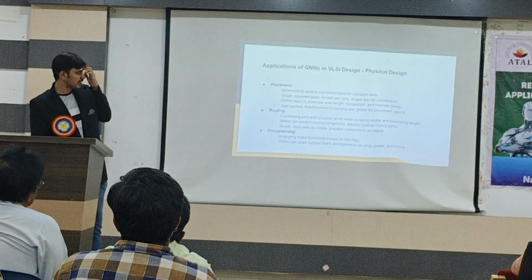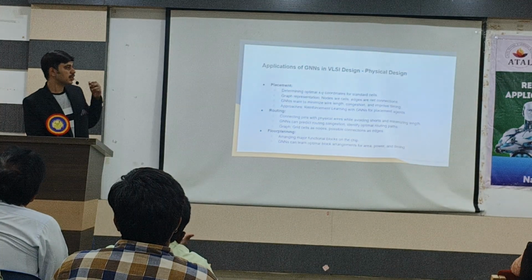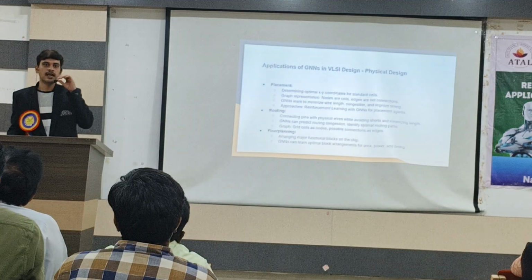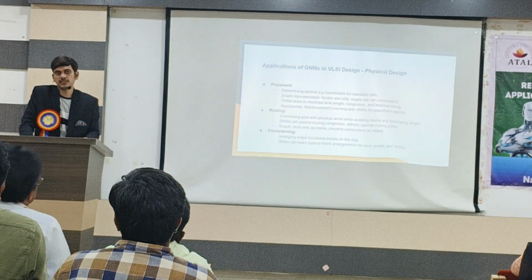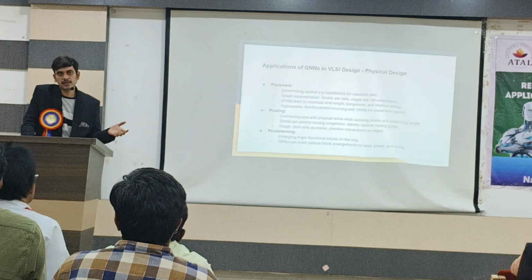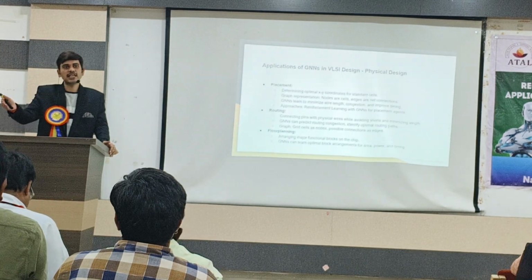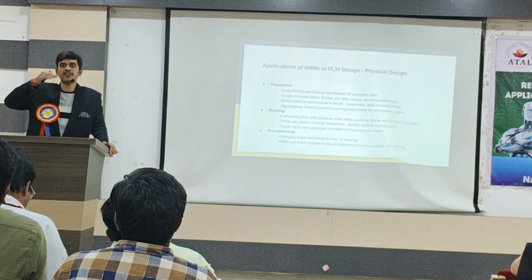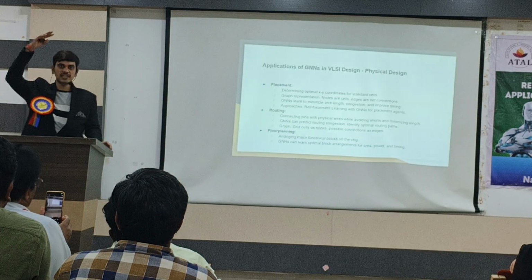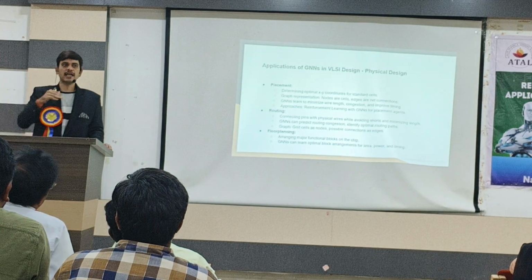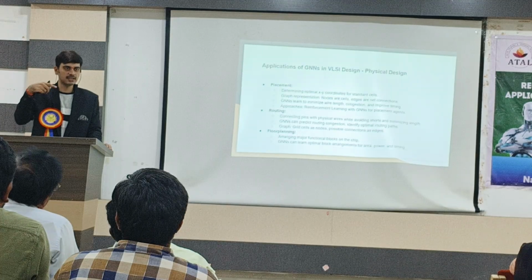So this is routing. Routing is another important thing, because we have heard about congestion, right? If it is more congested, if there is no space, we don't have the routing resources. Even if we have the placement, that should be routed, because the connections are doing the work. There are different layers like metal 1, metal 2, metal 3, stacked on top of each other. Some are horizontal layers and some are vertical layers.